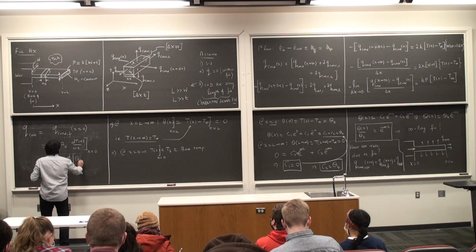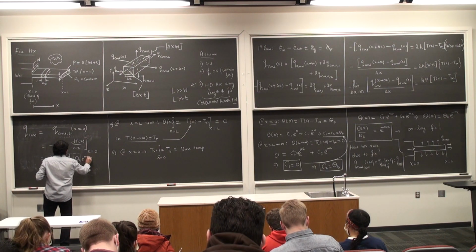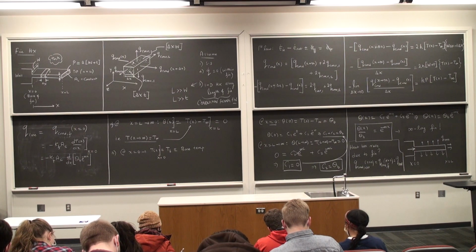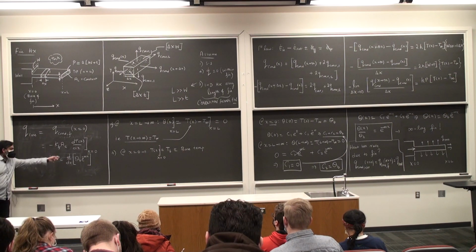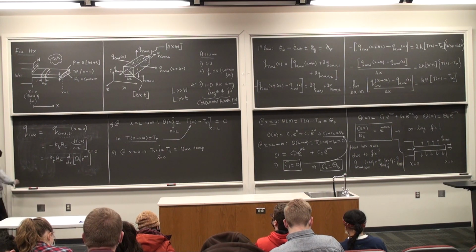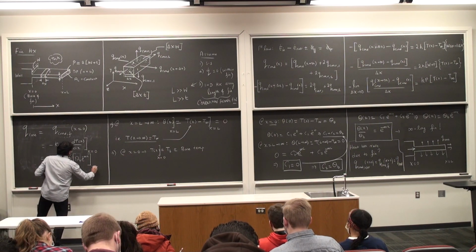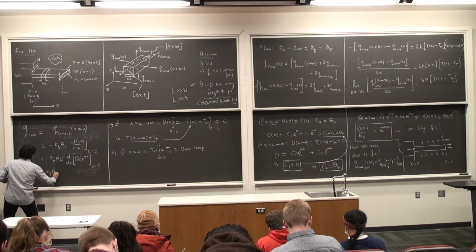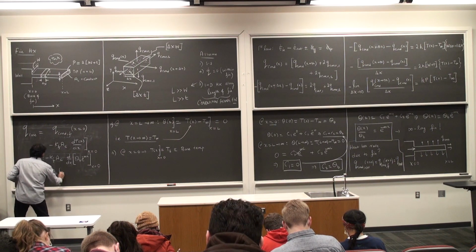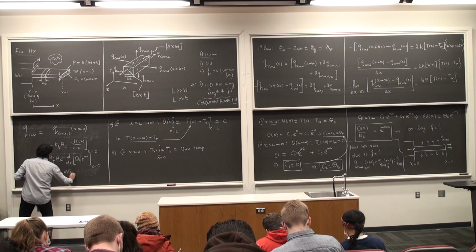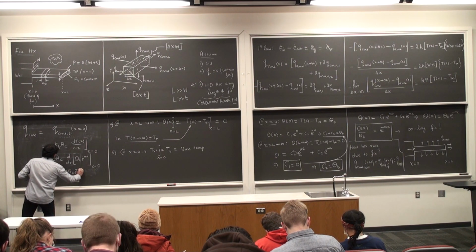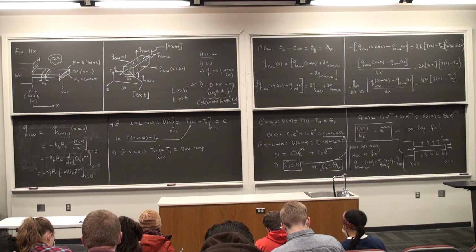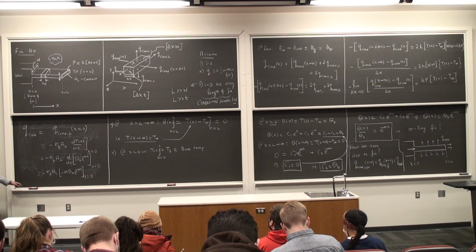So this is theta b e to the power minus mx, d by dx of that. And that's going to be minus m times e to the power minus mx at x is equal to 0. And so this is minus kf Ac times minus m theta b e to the power minus mx at x is equal to 0. E to the power 0 is 1. Okay?